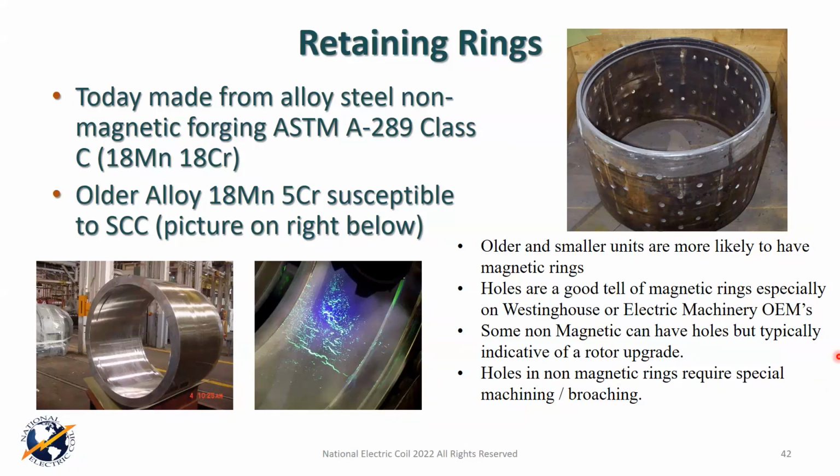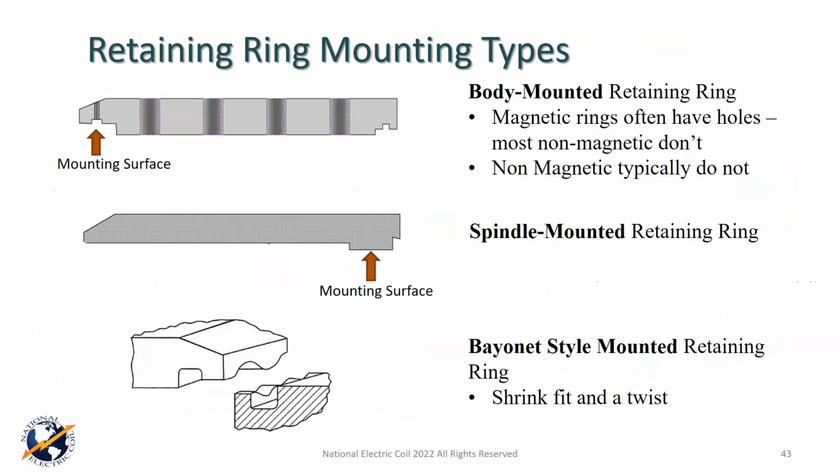And if you understand the design of the machine, and I'll get into the design of the retaining ring here in a moment, on the next slides, actually, you should be able to take it out with very little risk of damaging other components. Where the risk goes up is if this thing is highly corroded because it wasn't properly maintained or filtration wasn't maintained or whatever, okay? Or if they've had some failures that cause problems, yeah, there is a chance you can damage other components, but you typically don't have a lot of choice. You've got to take the thing apart, okay?